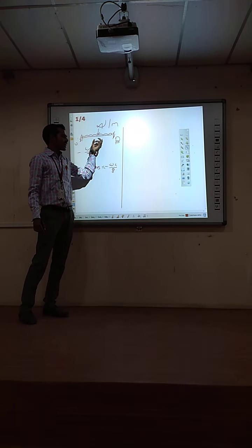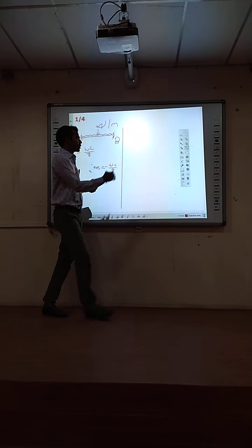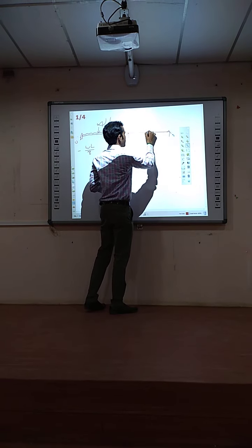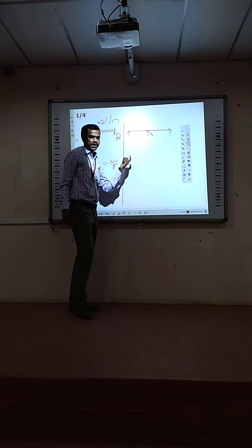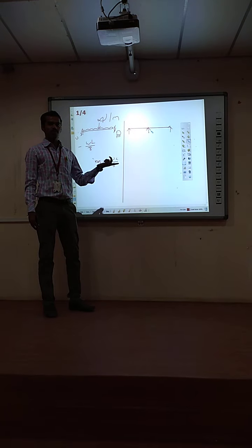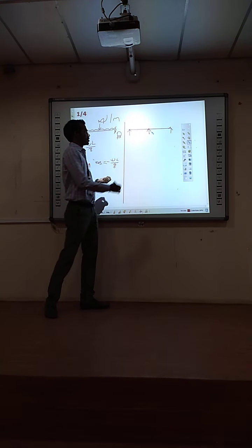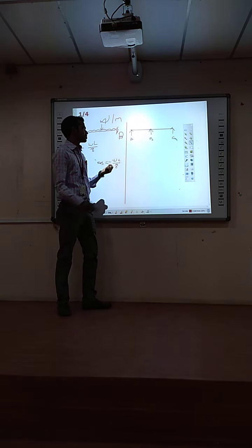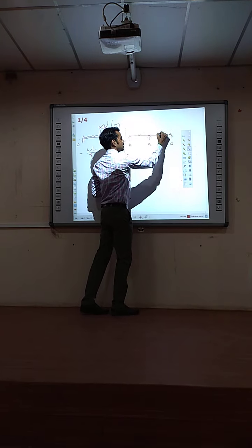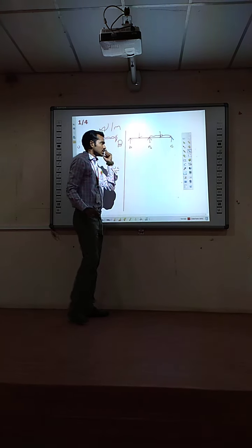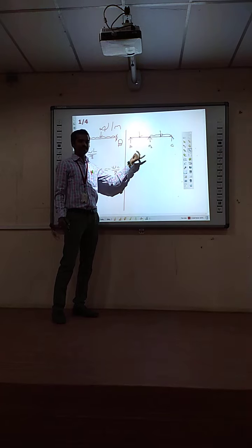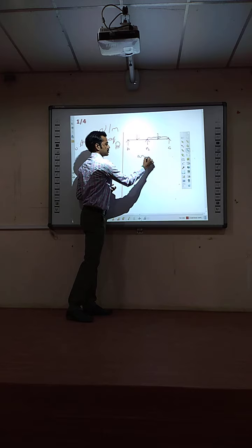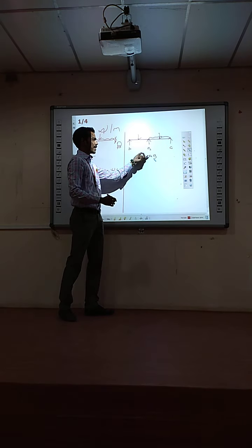So next step, we have to move on to the next beam, continuous beam. What does continuous beam mean? There are two or more supports. So A, B and C. In these continuous beams, various loads are acted. Point load, UDL. So we separate these continuous beams into two spans, span AB and span BC.